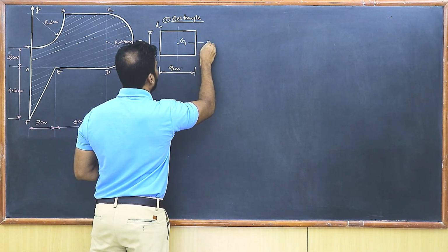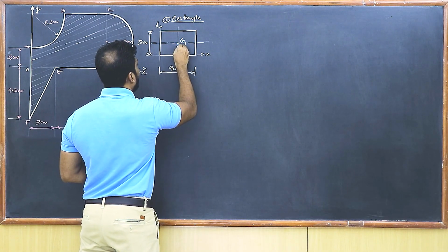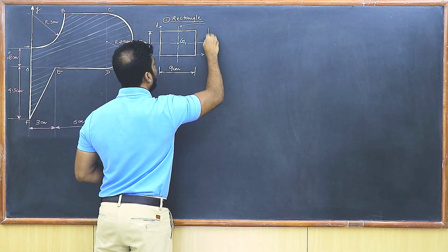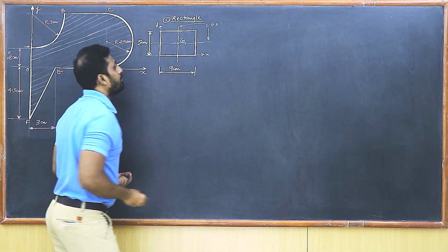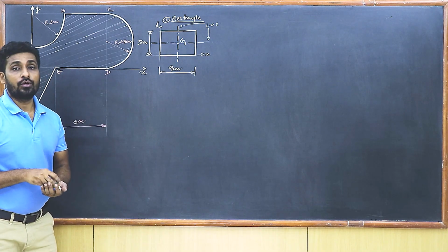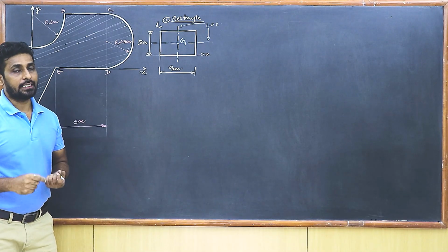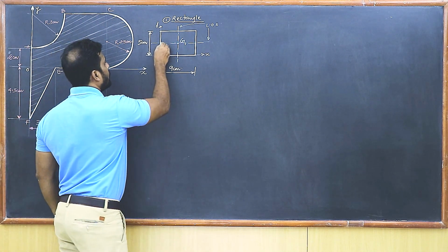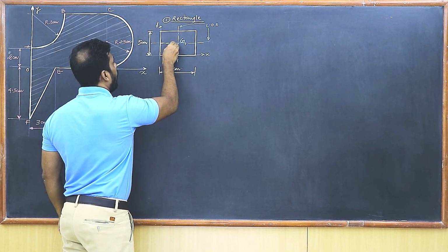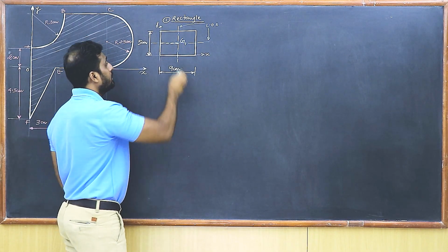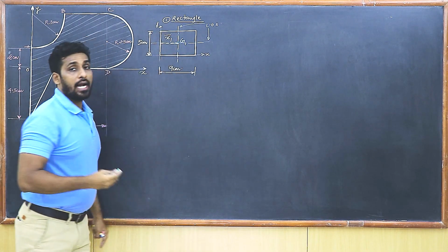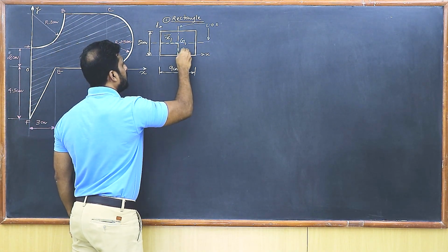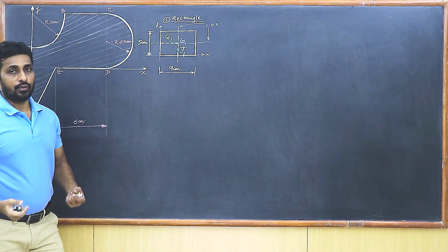So this is a line of symmetry, and this is the other line of symmetry, isn't it? So let's write it out over here that these are the lines of symmetry. Now I want to locate the coordinates of the centroid with respect to the original x and y axis. So I will be considering the distance of the centroid from the y axis. So this is the distance of the centroid from the y axis. That becomes the x coordinate. So that is x1 bar, and likewise you have the other distance. This is y1 bar. So I have x1 bar and y1 bar.